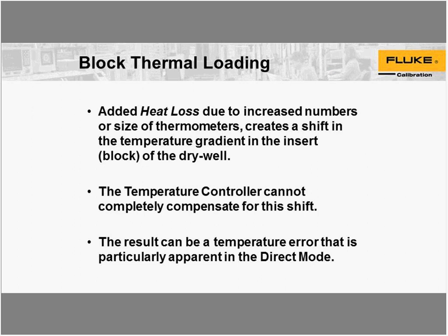Okay, thermal loading. What is that? As you can imagine, you add a number of thermometers to your insert or block, that will increase the heat loss, or heat gain if you're below ambient temperature. And the more loss or gain that you have, that can create a shift in the temperature gradients in the insert.